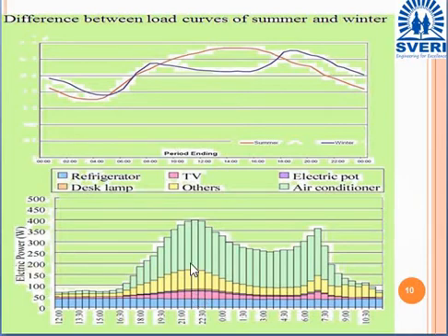And the air conditioner we use almost the whole daytime and some hours in the evening, and it will consume more load. That's why the use of the air conditioner will reach some of the peak levels during the day. So it is clear that with the help of the load curve we can calculate the load on the power plant during the day. We can draw a load curve for a single consumer, for the commercial sector, for the industry, and for each and every customer who is utilizing electricity to run electrical equipment or appliances.